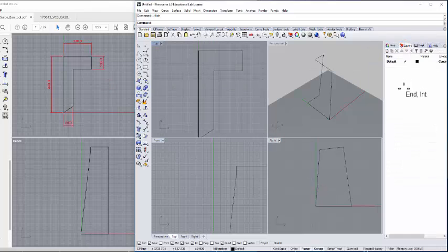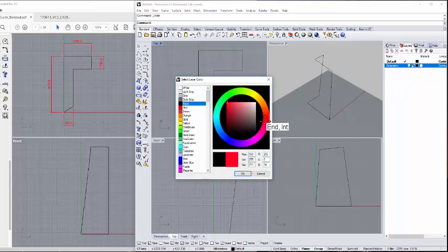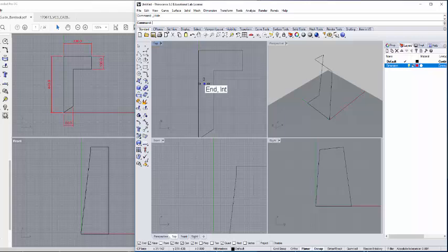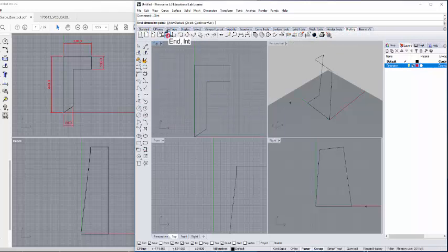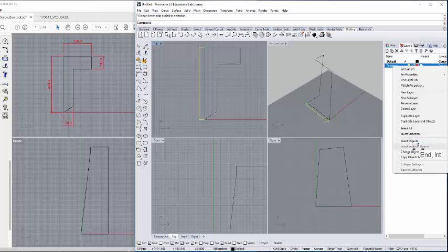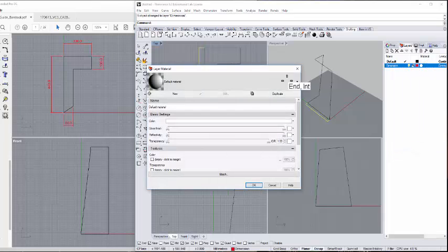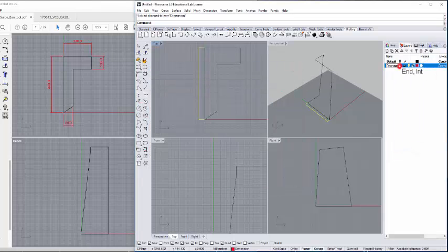Let's say I use the same one, which is dimension. Okay, I'm going to use red, and then I'm going to pluck out all the drafting lines just to make sure it's the same. So let's say, for example, if you can't see anything, change object layer, double click so that we are working at the same layer.